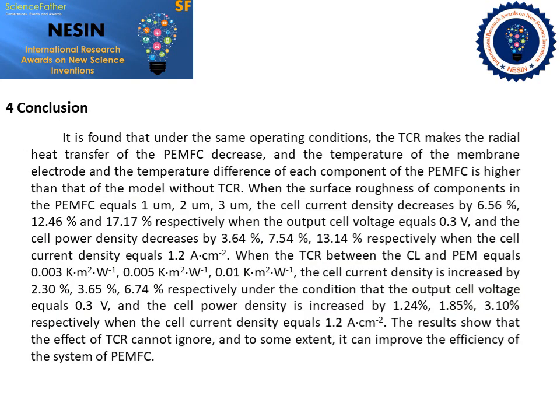The last is the conclusion. It is found that under the same operating condition, the TCR makes the heat transfer of PEMFC decrease, and the temperature of the membrane electrode and the temperature difference of each component of PEMFC is larger than that of the model without TCR.